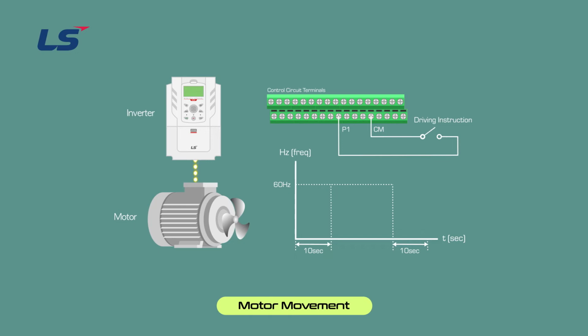Turn on the switch connected to P1. Trend waveforms, keypad, and motors show that it takes 10 seconds to accelerate or decelerate to 60 Hz.